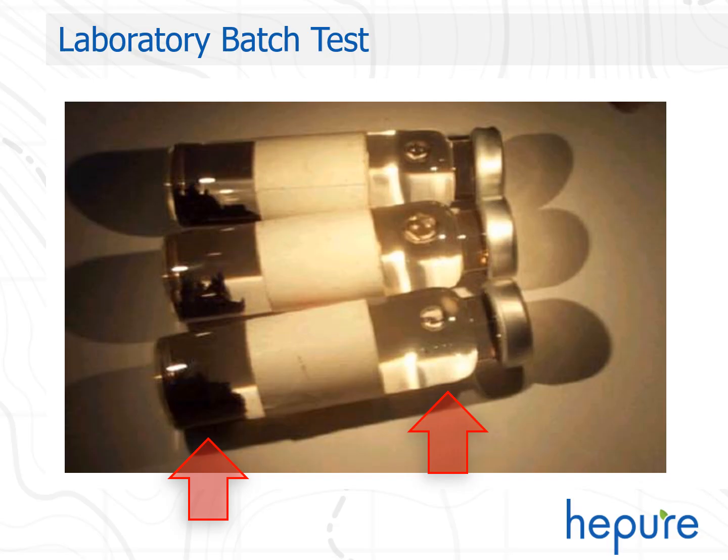We can get K observed and K mass by performing a batch test. A fixed volume of water is treated by a fixed mass of ZVI. Samples removed from a bottle are analyzed over time and provide the data for our regression to get K observed. And the volume of water and mass of ZVI will be used to adjust K observed to get K mass. That's the iron and the water, and we can collect samples.